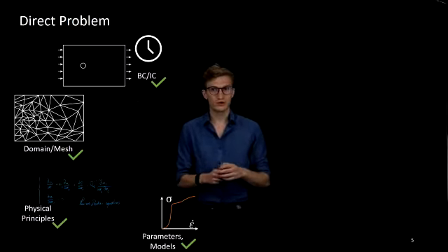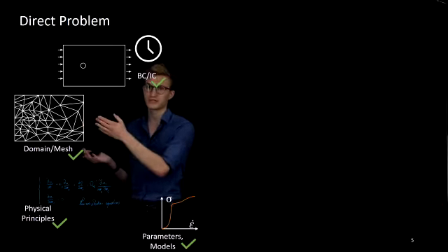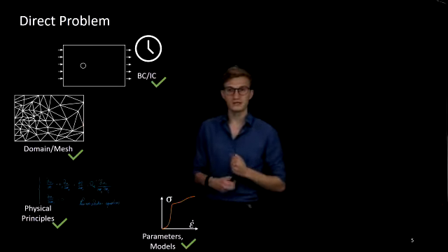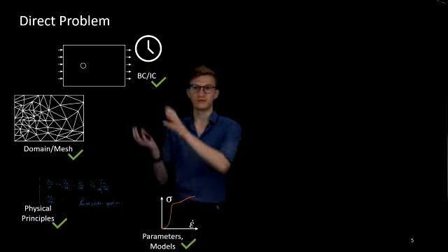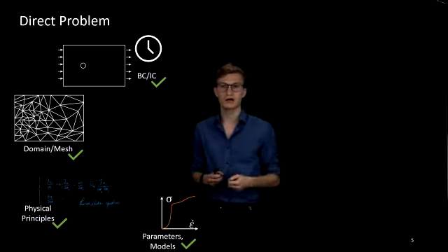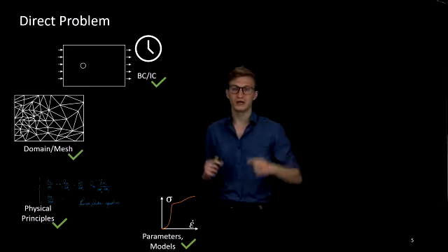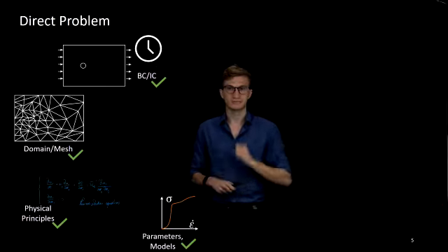So usually you perform a numerical simulation on a certain domain that you're able to know and discretize, for instance, with a mesh. On that domain, which is bounded, you have boundary conditions that are clearly identified, and also initial conditions, which is a given state of the fields of your variables at a certain time, usually the beginning time.